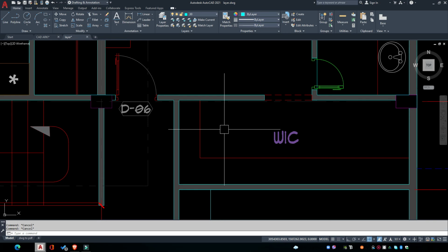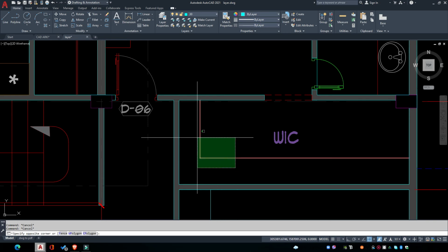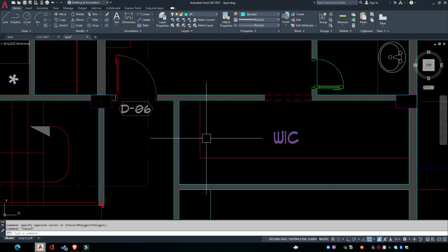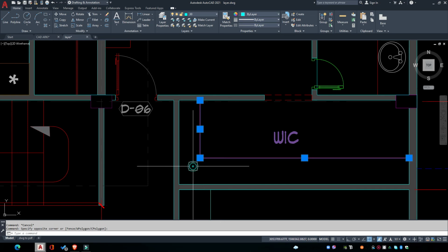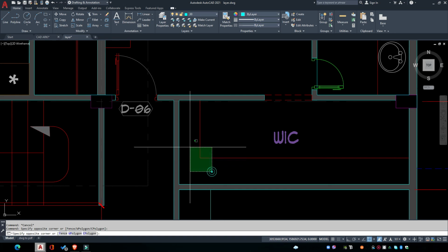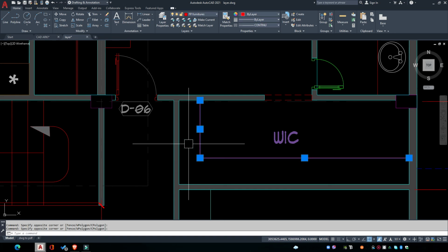Let's take this for example. Meron ako ditong mga lines. Lahat ng pula ko dito is under kay FP Furnitures na layer. So, ang gagawin ko ngayon, si FP Furnitures na layer ko ay 0.13 ng kanyang line weight. But then, meron akong specific line na gustong ibahin. Gusto ko gawin 0.15 tong dalawang lines na to. So, hindi ko pwedeng ibahin sa layer properties yung line weight kasi lahat mamaya ng under dun kay FP Furnitures na layer ko ay magiging 0.15.